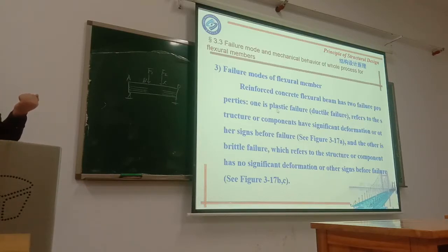So which mode do you think is more dangerous? Plastic failure or the brittle failure? Brittle. Because when it's plastic, we can repair, but if it's brittle, it's sudden. Yeah. So it happens suddenly. You have no time to react.